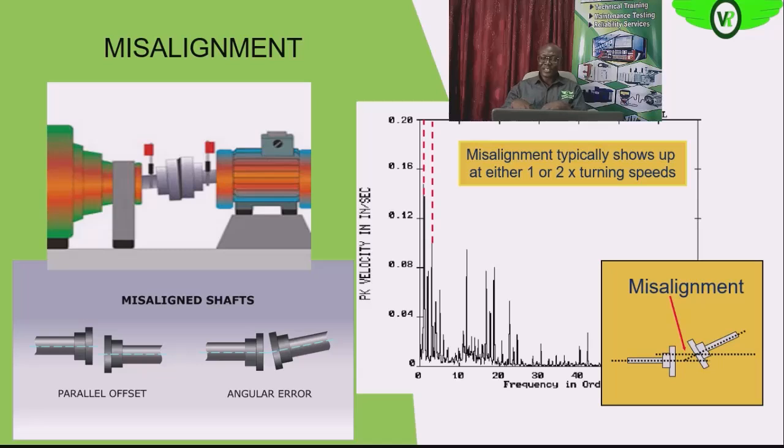We will be giving the electric motor more load than what we installed it for, because of that misalignment. All of this increase in loading will affect the entire system. Remember, it will increase the load current and the heating of the motor, and the heating of all the electrical components, cabling and what have you, on the line to the point of input.